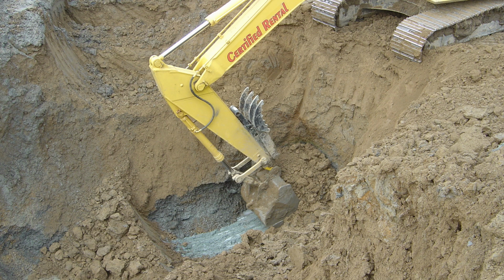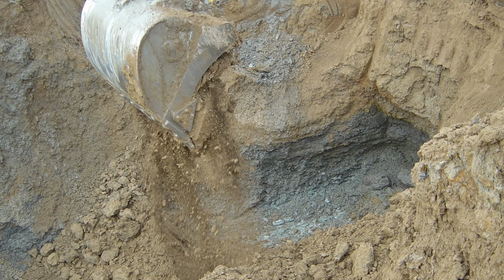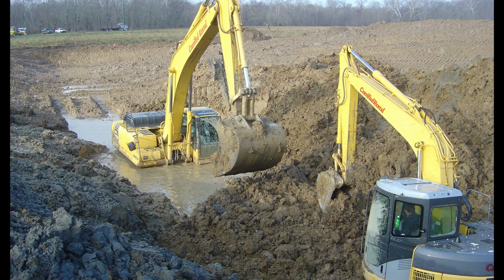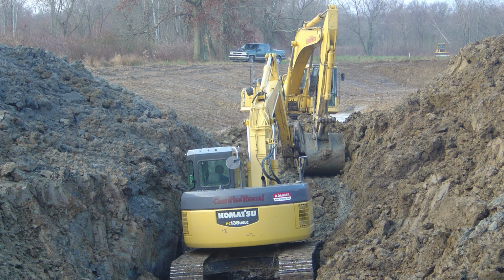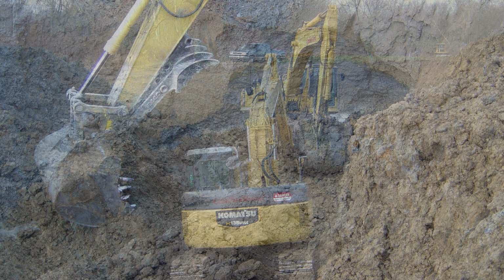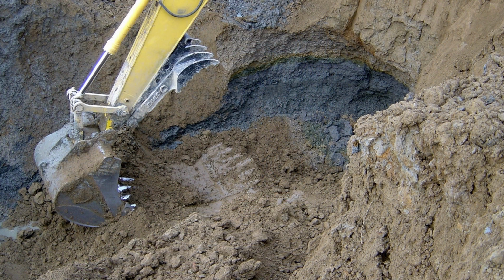The excavator operator moves quickly to place soil in the bottom of the trench before gravel caves in from the sides or water flows in and makes mud that can't be compacted. I stood on high ground overlooking the trench and alerted the operator when there was a cave-in so the gravel could be removed before the trench was filled with soil. Leaving gravel in the trench would have had the same effect as installing a drain pipe that would bypass the groundwater dam.